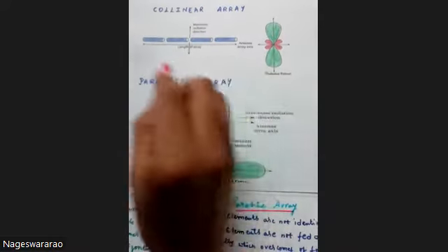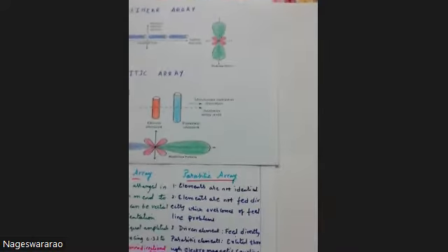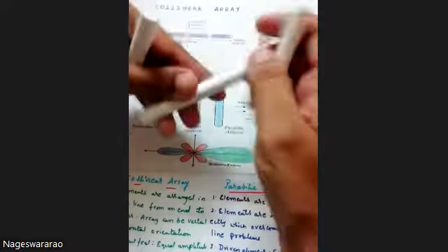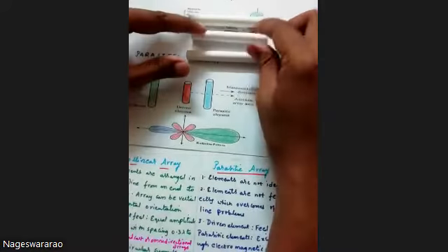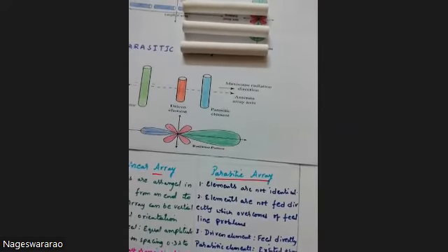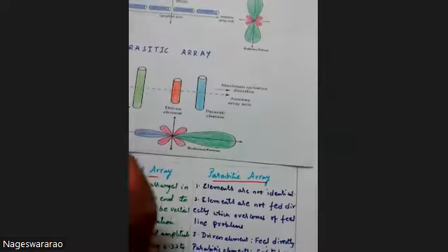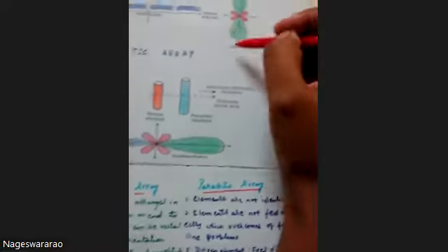Actually, this is exactly similar to a broadside array, but the only difference is the arrangement of antennas. In a broadside array, I said your antennas will be placed like this, right? But in this case, the antenna arrangement will be like this. Otherwise, antennas will be placed one above the other. We can call it a stack arrangement also. You can see the difference in arrangement of antennas. Because of that, otherwise everything will be similar to a broadside array, even including the radiation pattern.